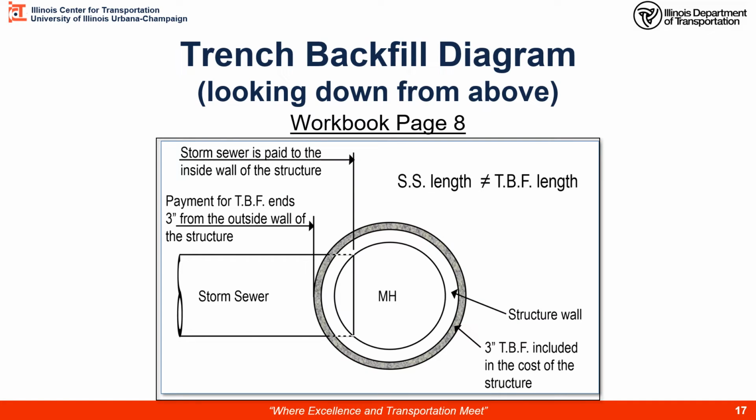Let's look at this manhole from above a little bit. Here's our manhole. Here's our trench backfill, 3 inches included in the cost of the structure. So when we determine the cost of trench backfill, the length of this trench, typically we measure up to the manhole, but then we need to subtract off 3 inches of trench because that's already included in the manhole pay item. However, the pipe itself will be paid for all the way through the manhole and into right where it